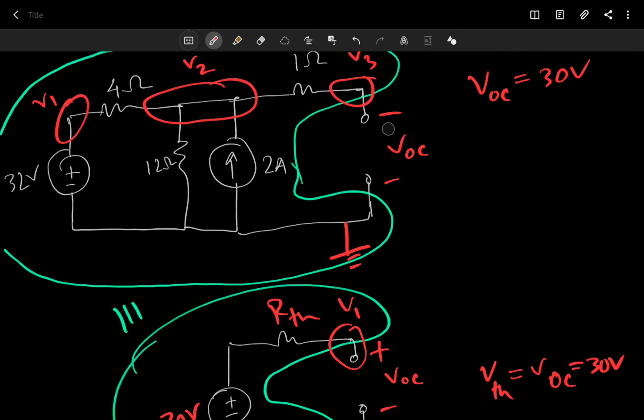Well, this time we use short circuit. If instead of opening the terminals we had shortened them, we wouldn't have any voltage difference, because there is no voltage difference across a continuous piece of wire. So that would be just 0. But there is some current, right? Some current will go from here to there, and that current we call I short circuit, ISC, the short circuit current.